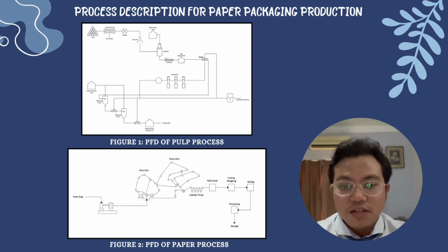Next, the pulp is cleaned and washed using a washer to remove some chemicals from the black liquor, and subsequently enters the bleaching tower for the bleaching process. In the bleaching process, the washed pulp is bleached using chlorine dioxide to give a whiter, cleaner color. The bleached pulp is refined and stored in a bleached pulp storage tank. The remaining bleaching agents mix with black liquor and are sent to the wastewater treatment system. The bleached pulp then undergoes paper manufacture for the paper making process.